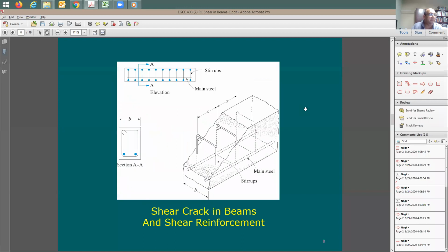How do you hook it to something here? You put these hooks like this, and then you put a rebar inside the tie itself. And with this rebar within the tie itself, it's going to stop it from coming down. So this resistance wouldn't happen unless you have a couple of rebars right here at each corner. You're going to put one rebar here, another rebar in this location. Without these two rebars, these ties are not doing anything for you.